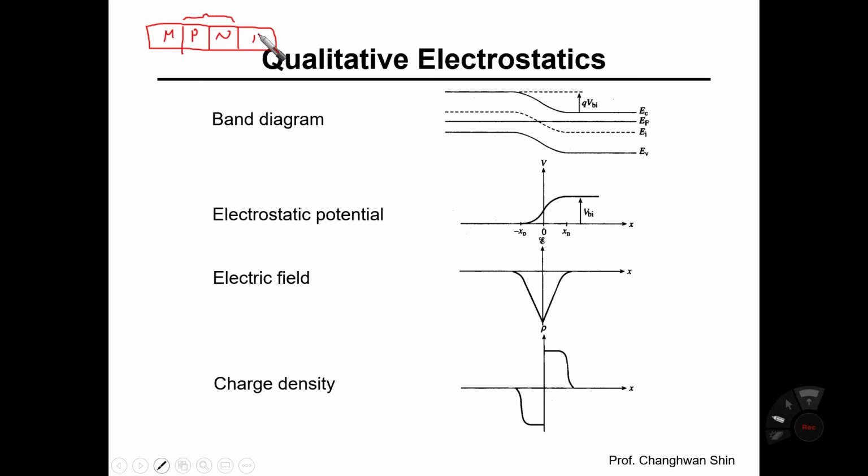Actually, the metallic material would be bonded or deposited onto the P-type and N-type. But since the P-type region comes from the wafer substrate, we need to make an ohmic contact.